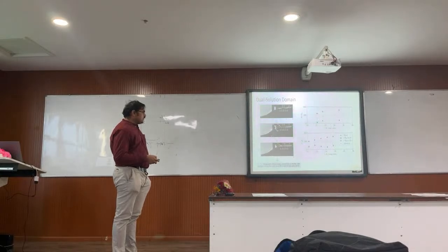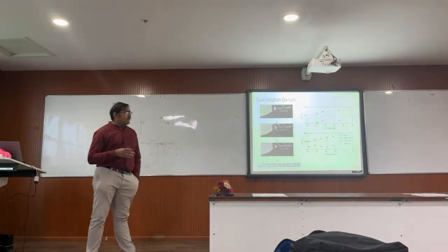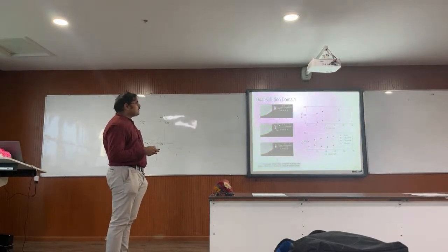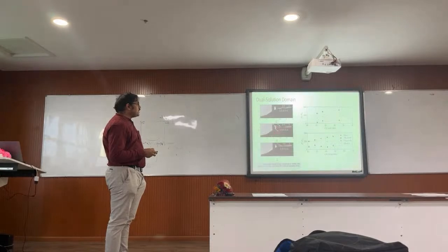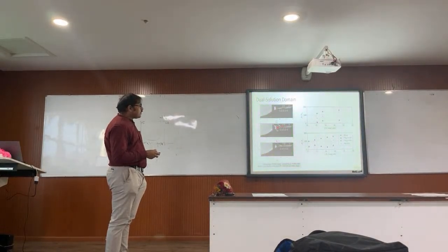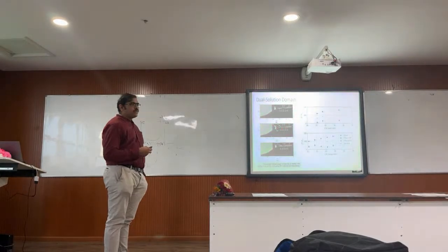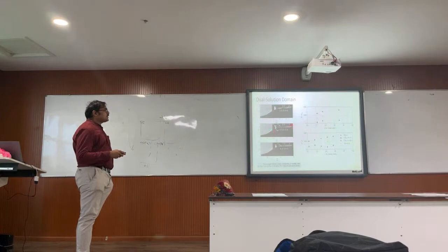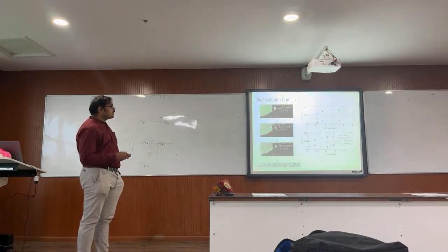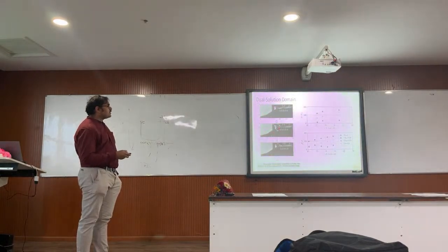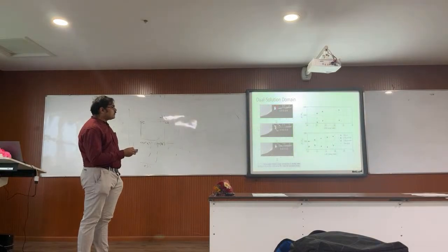But in the second case, we fixed the flap at 0.35 and then started the flow, and we found that the pressure ratio was much higher. We see a strong shock that sits ahead of the cowl here, and it produces a kind of supersonic jet over here on the top side of the wall, while at the bottom side it's a subsonic flow. And this pressure is much larger than the standard case, so it goes into unstart. There is actually spillage, because from here there is a separation, and the cowl shock just comes out and is no longer attached like what is over here.